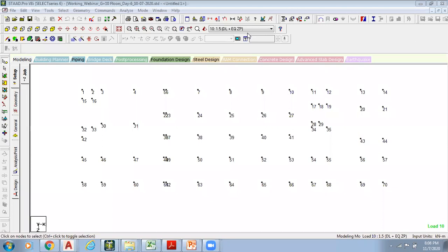For design of foundations, we will not be using the reaction for 1.5, nor should we use only the foundation combination maximum reaction. We have to consider all the load combinations for foundation design. Anyway, we are not talking about foundation for this webinar. Envelope we will discuss after some time. We'll talk about flow diaphragm, not now. I remember it.